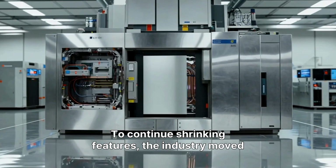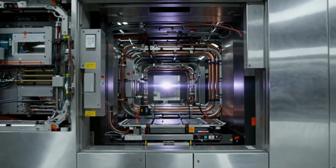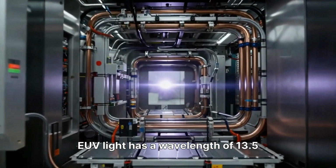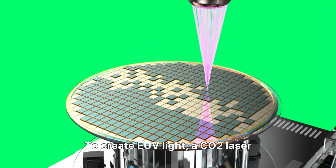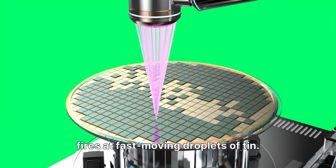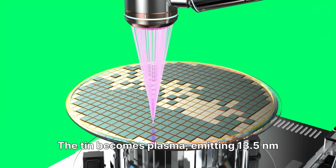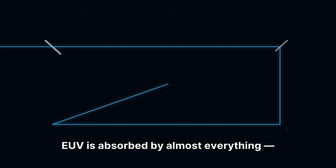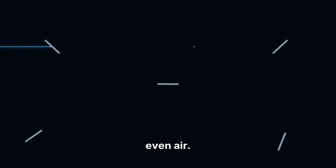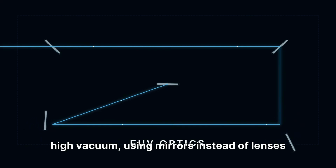To continue shrinking features, the industry moved toward EUV, extreme ultraviolet lithography. EUV light has a wavelength of 13.5 nanometers, almost in the X-ray range. To create EUV light, a CO2 laser fires at fast-moving droplets of tin. The tin becomes plasma, emitting 13.5 nanometer light up to 50,000 times per second. EUV is absorbed by almost everything, even air, so the system must operate in a high vacuum, using mirrors instead of lenses to guide the light.